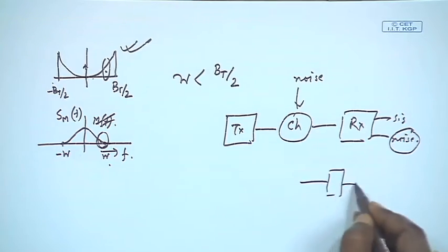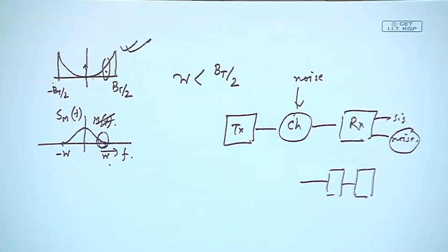So, basically that will distort the signal. So, if I have boosted it, I need to put a de-booster or some filter which is just cancelling out this boosting at the receiver. So, the fun begins when I start putting that. Suppose I have a receiver, after the receiver I put that reverse thing, at that time what will happen?